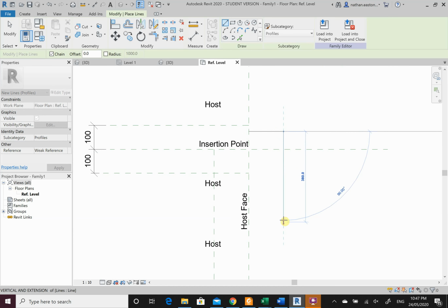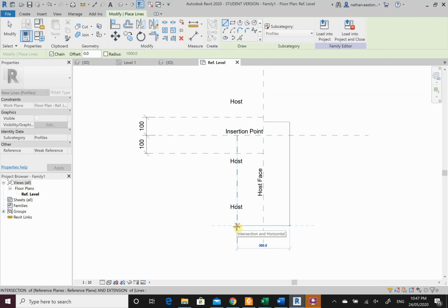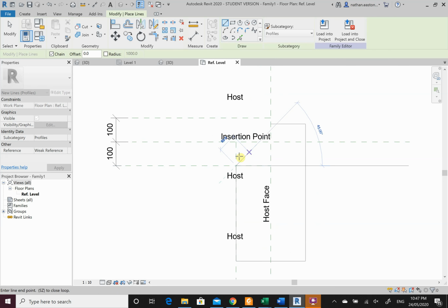Okay, and then come down. Remember, my footing depth I'm going to take is, say, 600. This footing depth is measured from the top of the slab. So it's 575 from the top. And then I'm coming across 300, which is going to get me to this line for the thickness of that footing. Then I'm going to come up to where it meets the bottom of the blinding sand or my bench level. And then I know from here it comes at a 45-degree line, which in this case, if that's 90, it's 135, until it reaches the bottom of my slab.